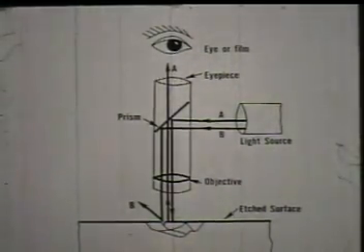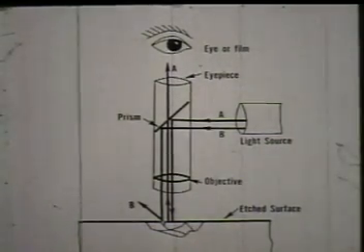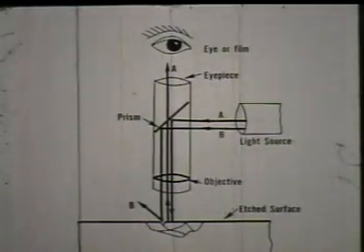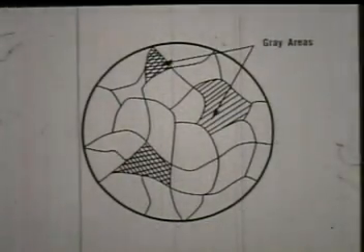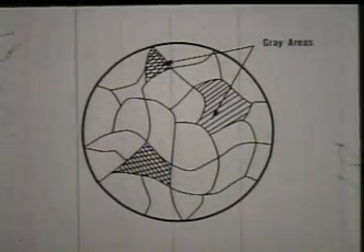Thus, the grain boundary becomes a depression or valley around the grain. Light beams such as B are then reflected off at an angle and not up through the microscope tube. Therefore, the grain boundaries appear as black lines surrounding the white grains. If the specimen is over-etched, the surface of the central portions of the grains become rough, and the entire grain appears gray rather than white.